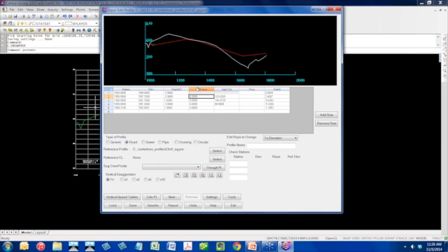Now my vertical curves, because it's a road type, it's giving me a chance to enter a vertical curve. So I'm just going to put 100 in for each of these. Keep it simple. And that's all there is to it. Now, as I've got this new one in, as I move my mouse along it, the crosshairs are going to chase that proposed profile. Notice at the top it's reading just that profile information.